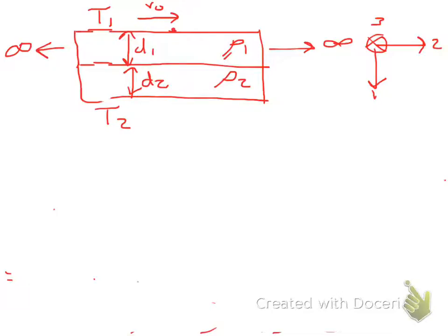It probably doesn't matter. That's our origin though. Steady state condition. They assume that this is 0 on two sides. So we have T1 at the top and T2 right here, and it's a straight line between if they have the same properties. So what was different if they have different properties? At that boundary, the slope would change. And which way it changes depends on which one ends up being more conductive or non-conductive